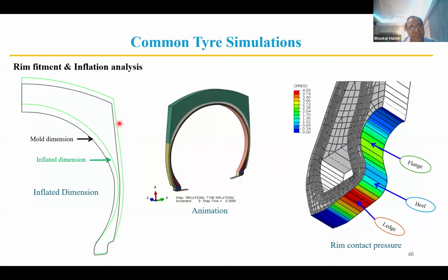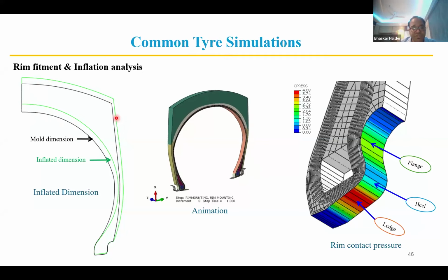Prior to that, designers had their own experience, or some previous experience data that yes, these tires have a growth of say 2% from the mold. So nowadays, if my material model and the tire models are perfectly okay, then I can predict what my inflated dimensions will be. And so the designers are getting more confidence in releasing the products in terms of dimensions.